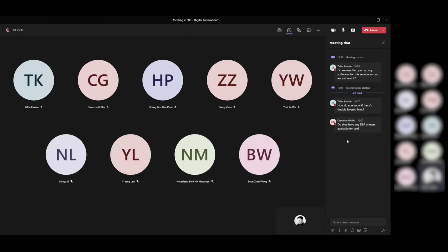Make2D is a fantastic command. It's my absolute favorite Rhino command, because what it does is it will see everything at face value. So it sees what's in front of you, and it will redraw that to its closest interpretation, and it does it extremely accurately. So even if you did have lines that overlap each other, but maybe aren't duplicates, this will still join those together and give you super clean geometry. So again, it's a good way to work. I would always use Rhino for fabrication. It's just the best thing out there.